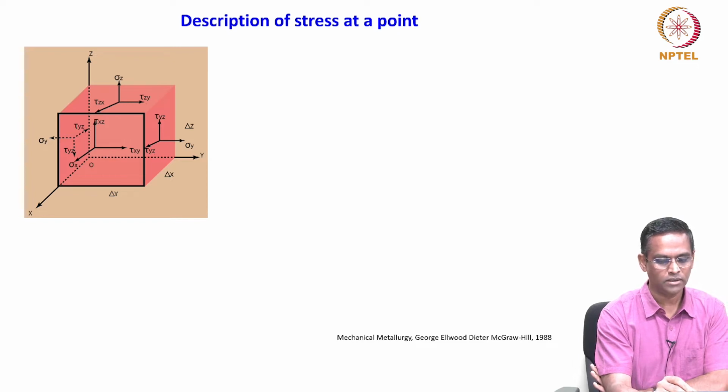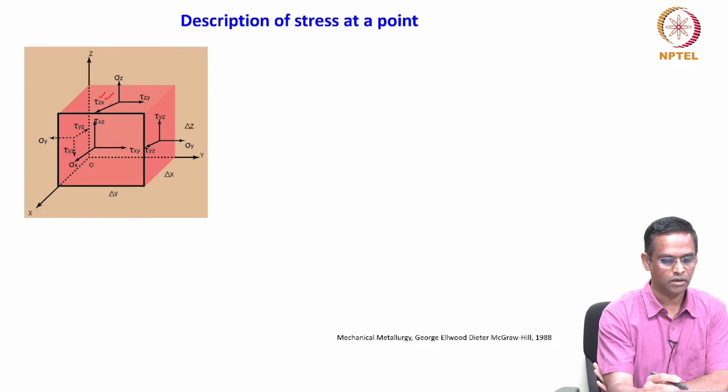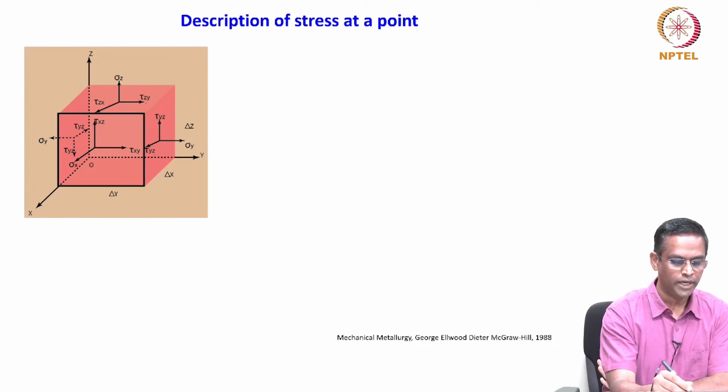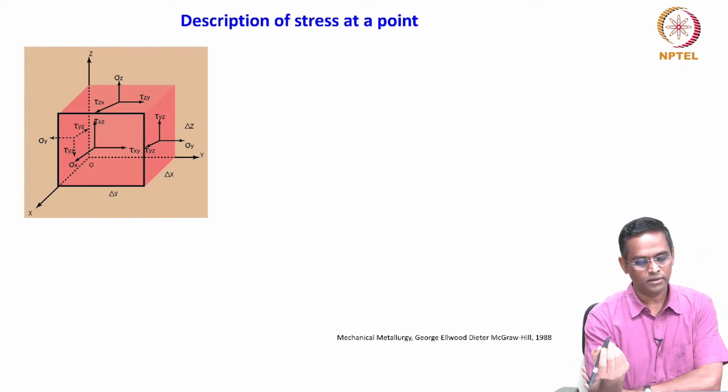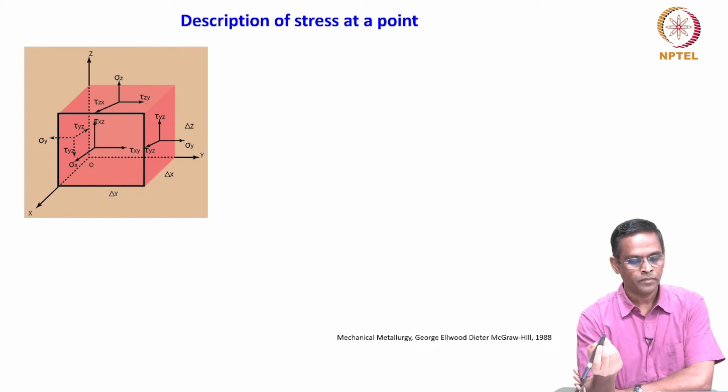Take this shear stress: it is in the z plane, so the first subscript is z, and it is in the x direction, so zx. So you need two subscripts to describe a shear stress.